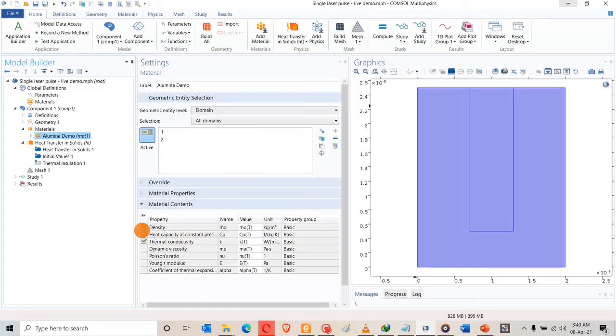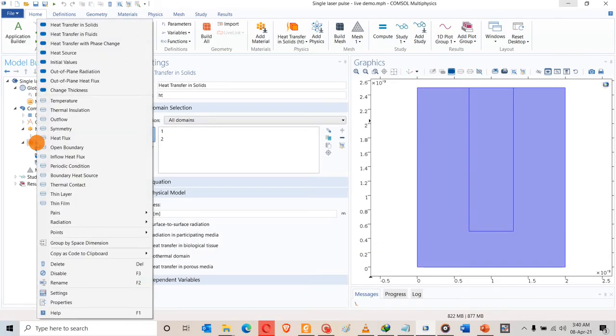Okay, already it's selecting the parameters that it wants, the heat transfer physics, which is good. We're moving on, we're saving. Now we're here. Here, what we want is to insert the most fundamental. We're not going to complicate it and introduce phase change yet. We're just going to include a heat flux and heat loss by radiation and another term for cooling.